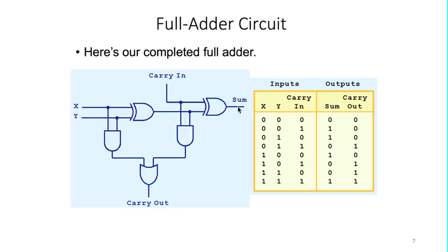So that's the sum. Now we have the 1 right here, we have 0 right here, the output equal to 0. Another output of the other AND gate equals 0. So we have the 0, 0, and the output of the OR gate with two inputs 0 equals 0. So the second row has been verified.